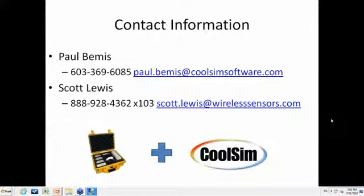I guess that just about does it for questions. One question you didn't answer was the communications protocol between our gateway and other DCIM applications. We can use SNMP, Modbus, TCP, ODBC, OPC, if any of those mean anything to you. So most of the standard protocols that DCIM packages will support, we will deliver.